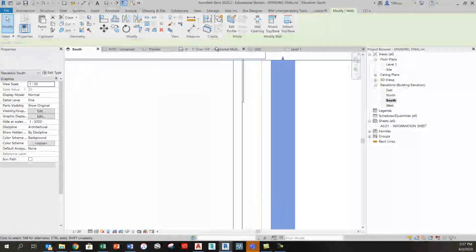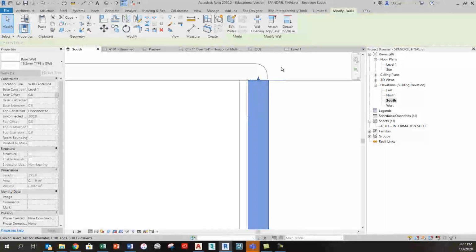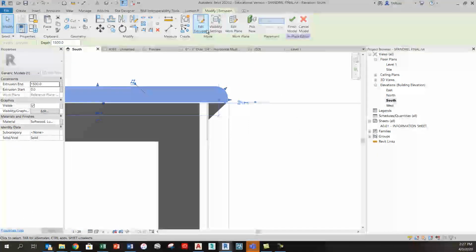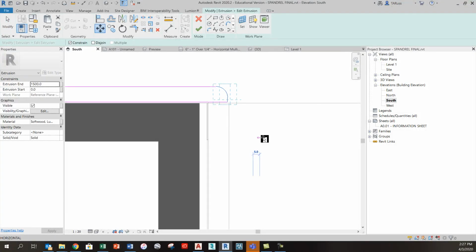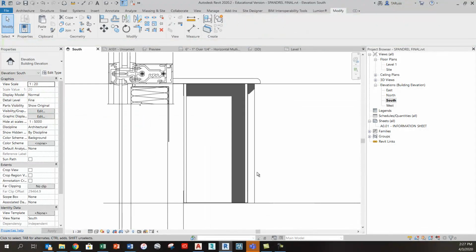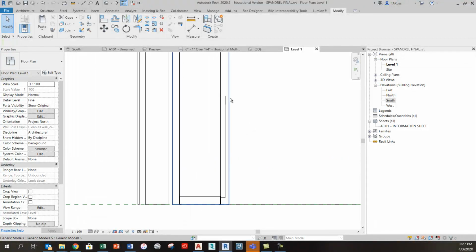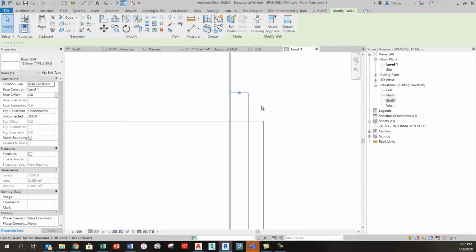And I can see here that I should actually increase the length of my millwork, which I can do fairly easily here by just editing in place, editing the extrusion, and then just stretching this fillet out a little bit. Something that might look like that. And then the last thing I want to do here maybe is just specify a different length for this gypsum wallboard, so maybe it matches up with the rest of the extrusion. And there we go.